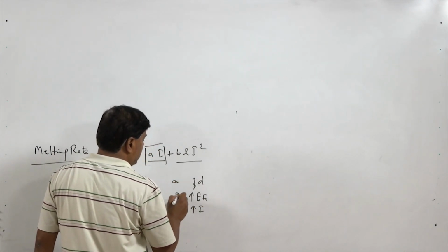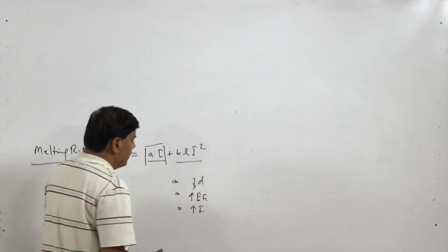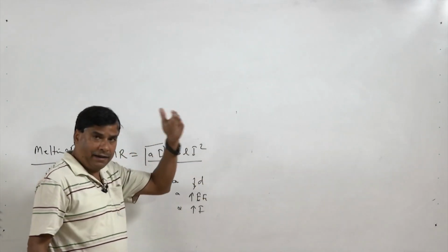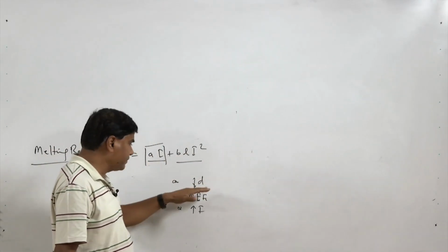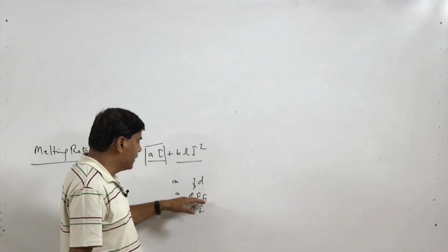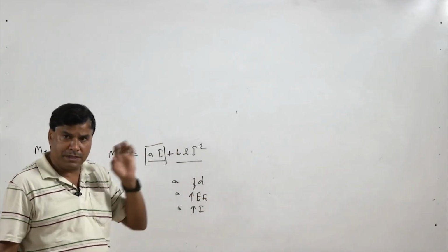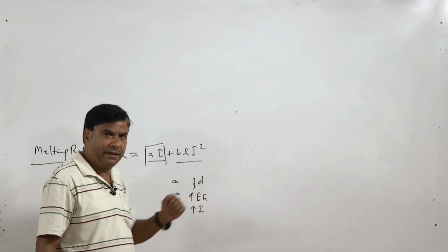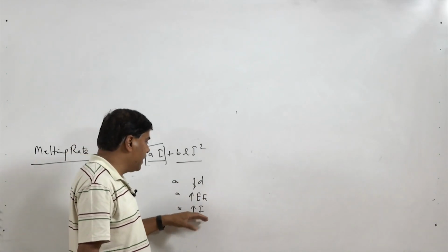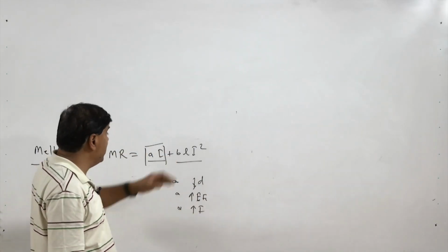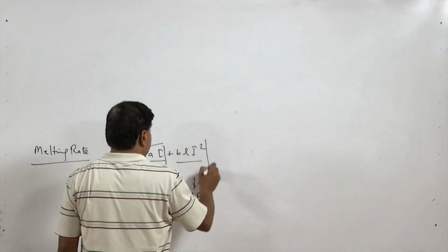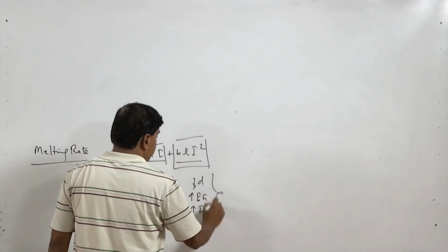So, for these three situations, a small diameter will result in higher electrical resistance to the flow of current, and greater electrode extension will offer more resistance to the flow of current. So, higher electrical resistance heating, and similarly a higher value, will cause more melting due to the second factor. So, the second factor dominates under this set of conditions.